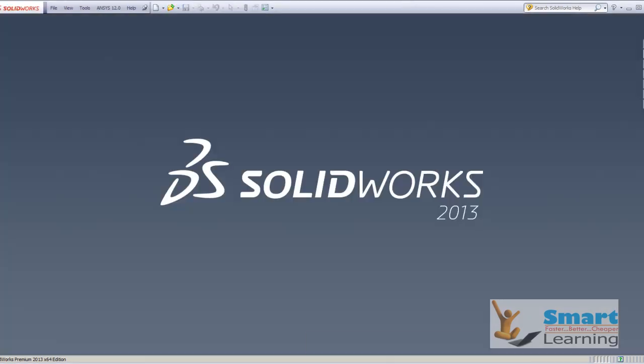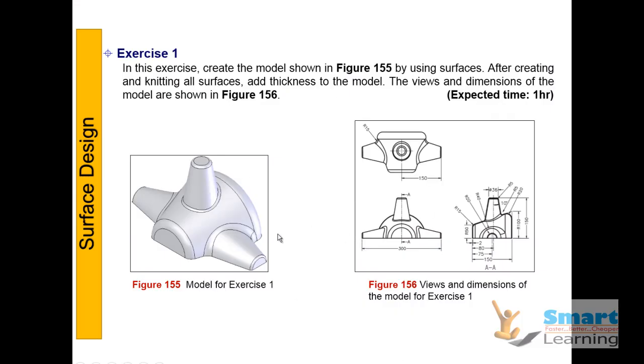Couple of exercises are there for your practice which you can choose from here, and you can create this same. You can directly go for the extrude and then you taper it. Here also extrude and taper it, or you can revolve it and create it and then merge it, then apply the fillet, then knit it.